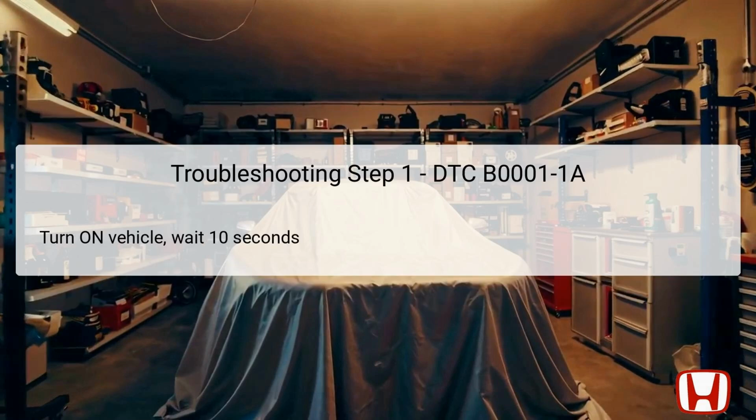The first step in troubleshooting DTC B0001-1A involves turning the vehicle ignition to the on position and waiting for at least 10 seconds. This allows the vehicle's onboard diagnostic system to initialize and check the status of the SRS components. The system will then perform self-checks and can reveal whether the DTC is still present. If the DTC appears again, it confirms that an issue is indeed present within the airbag system.